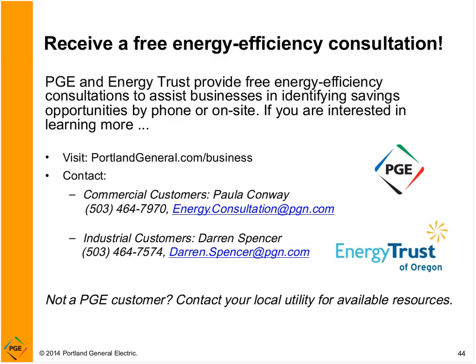A good example is PGE streetlights. Since we normally visit the light pole about every 5 years, we have a photosensor that lasts about that long. So when we change the lamp, we also change the photocell. But now, since we're going to LED street lights that are going to last a lot longer, we're not visiting that pole every 5 years like we used to.